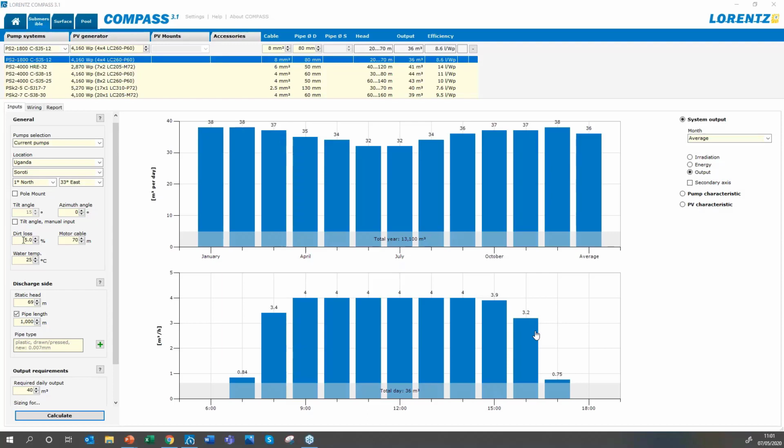The solar panel itself is going to be sitting exposed, of course. It's going to get dust collecting on it. If you have rain, they get cleaned. If you have a weekly or monthly cleaning regime, they will stay very clean. If they're left to get dirty, the dirt on it acts a bit like wearing sunglasses. It reduces the amount of light hitting the solar panel and reduces the amount of electricity it generates. So the more dirt and dust that sits on top of the PV module, the darker the sunglasses, the less power is generated.